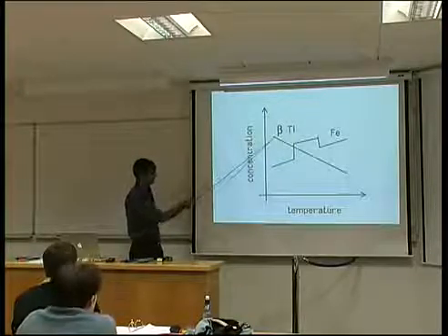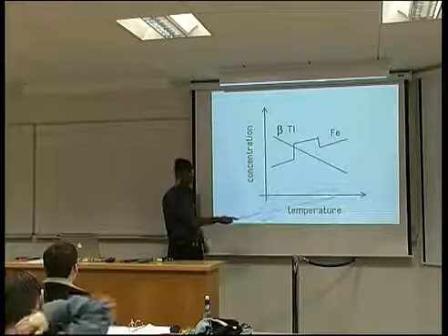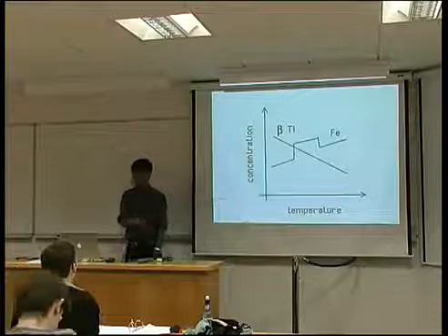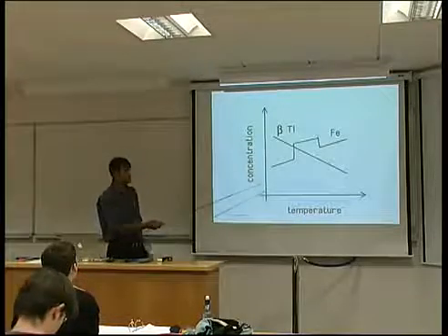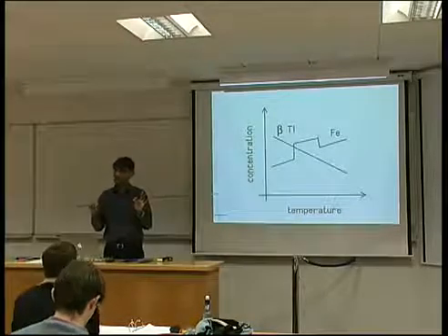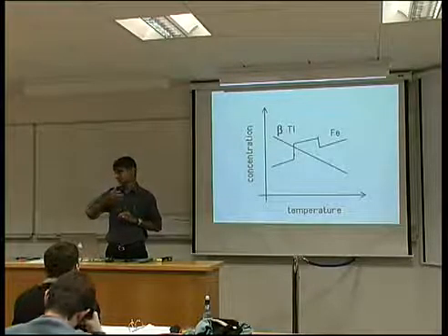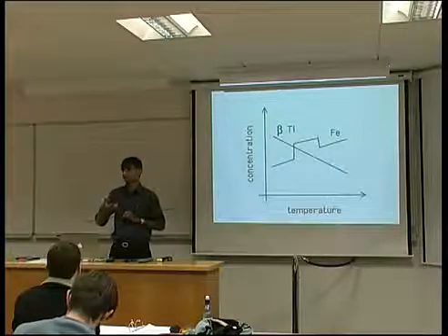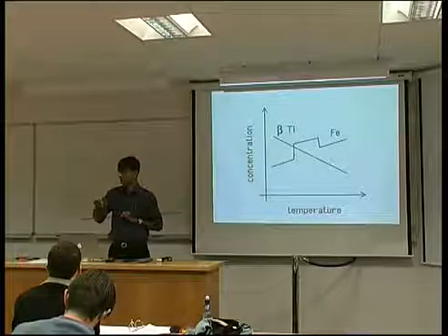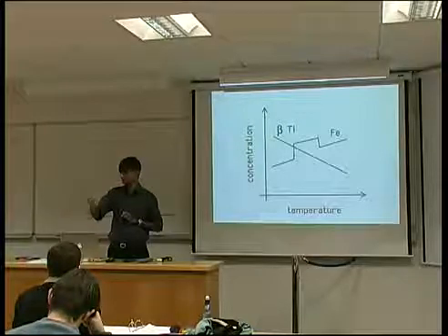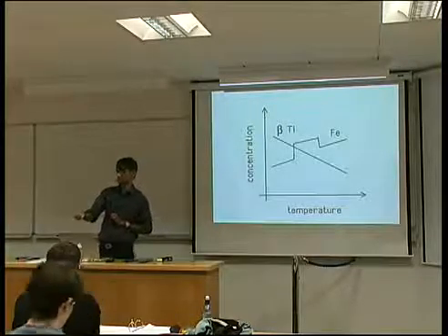The other characteristic is that hydrogen solubility actually decreases as you raise temperature because of the sign of delta H. Now that means that we can potentially use it for construction of the fusion reactor, where there's a lot of hydrogen around. So at high temperatures, titanium is not embrittled by hydrogen because the solubility decreases at high temperatures.